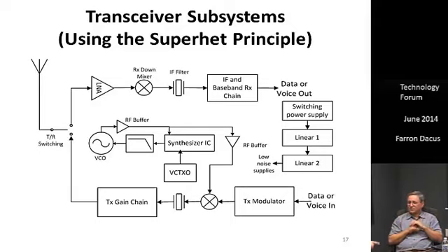There's no coming out of the chip to a filter and going back in. Yeah, but the problem with even direct conversion, where you can get very low bandwidth at baseband, is that you've got phase noise on the oscillator that does the converting. And that phase noise, I'll show a graph of it later, is coming up as frequency comes down. And so you reach a point where you become phase noise limited in sensitivity.